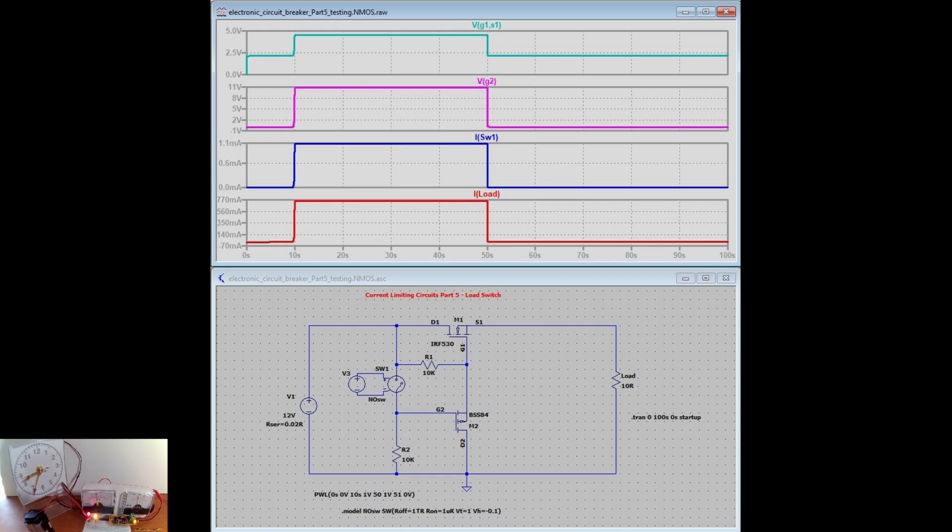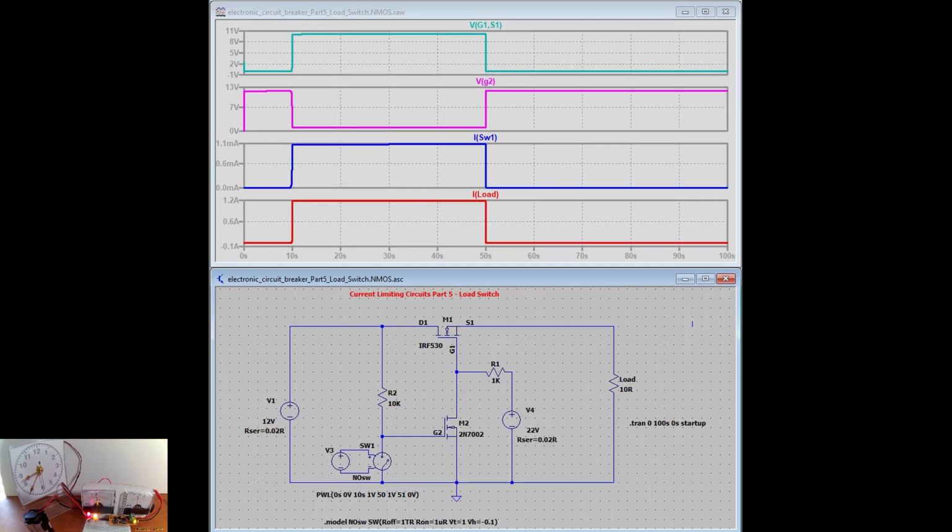voltage of the MOSFET. For that we need additional circuitry like 1. Additional power supply with a voltage higher than the gate threshold voltage, plus the main power supply voltage. In the picture, for a 10 volts gate to source voltage we need an additional 22 volts power supply. Most of the time this is not possible, or convenient.